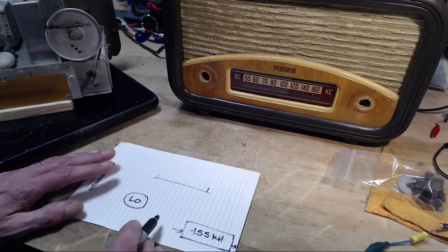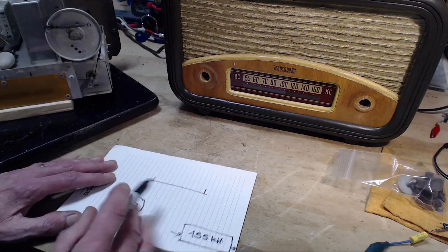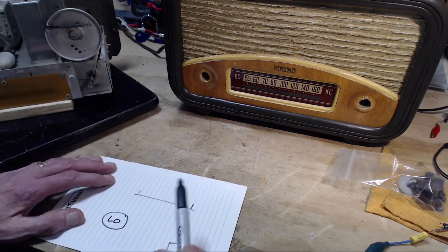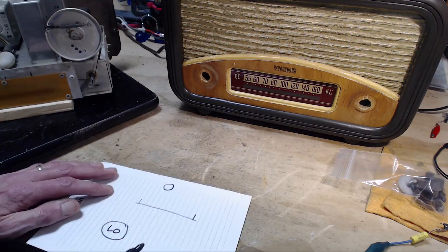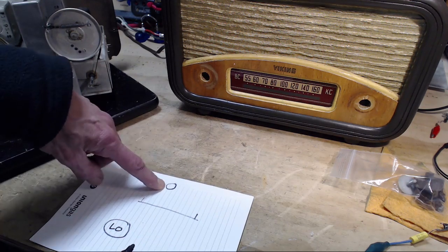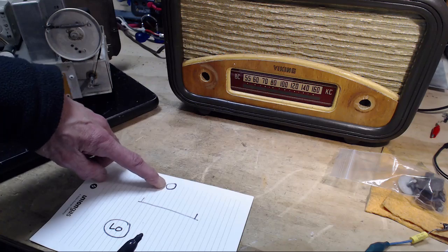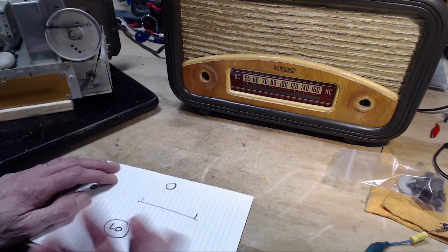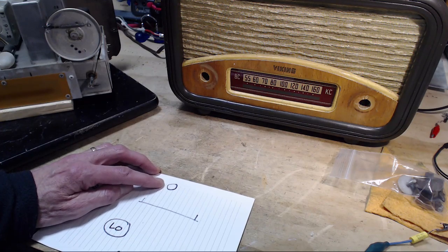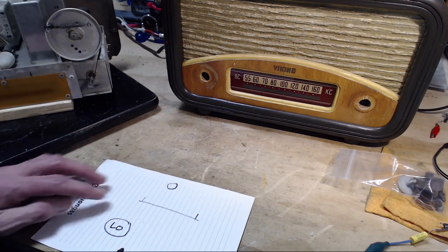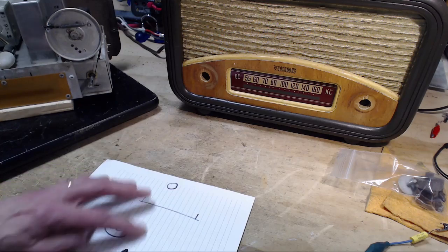Now, how does that work? How do you manage to convert it? So you have a tube. I'm going to draw it up here. So this tube in radios has varying names, functional names. In North America, commonly this is called the mixer tube. It's mixing a couple signals. It's going to mix the signal from the antenna with this local oscillator.